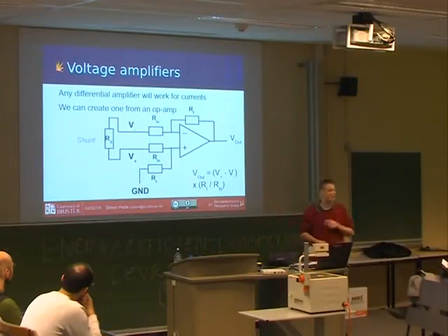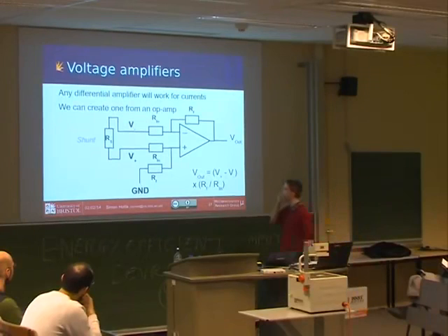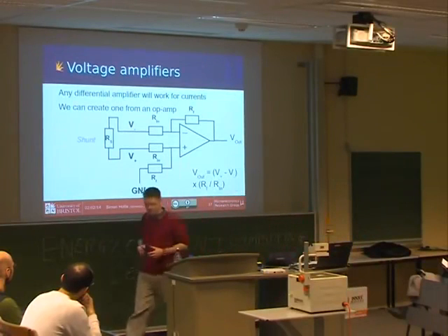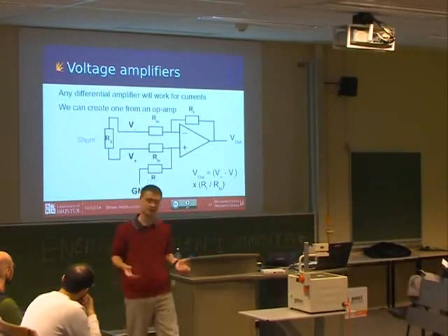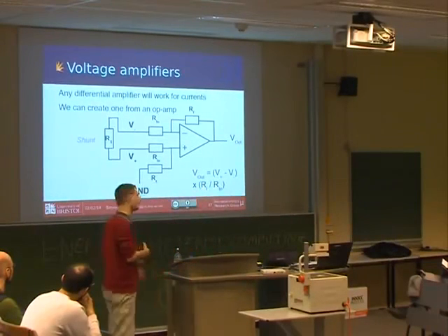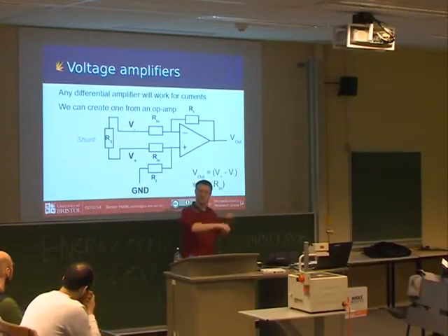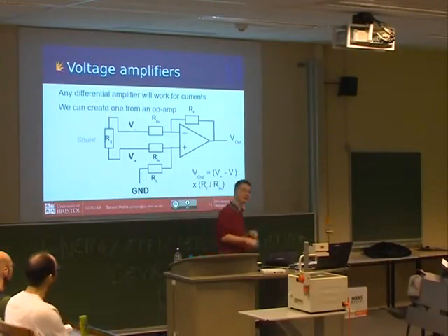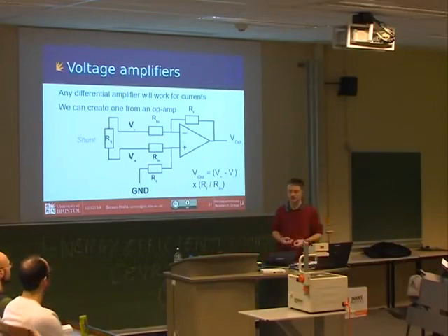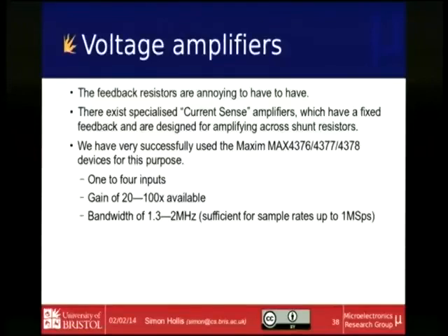The downside to this is, when I started thinking, well, shall I build this circuit, which would make boards based on it, you find out weird things, like the fact that the 4 resistors here add more cost to the assembly of your measurement board than it does to buy the operational amplifier. That's because essentially the robot has to go to 4 more places and put 4 more resistors, and we've got 2 different values, with an actual cost to making it. So if you wanted to mass produce this, it's less attractive. And it's annoying, breaks our layout, doesn't look so pretty, all sorts of things.